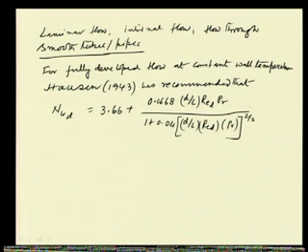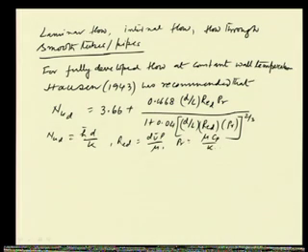Now, here as I already told, the Nusselt number is based on diameter and it is h d by k, and this h is basically the average heat transfer coefficient throughout the length of the tube. So, h bar, and ReD is d v bar rho by mu, and we know that Prandtl is equal to mu Cp by k. All these things are known to us.